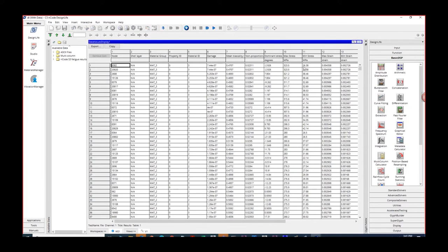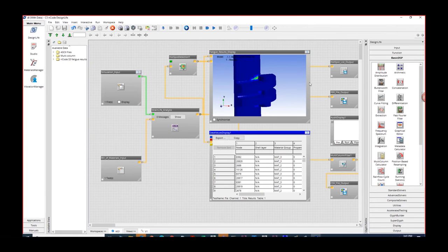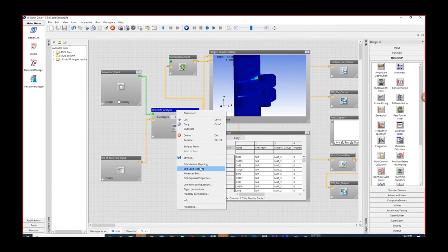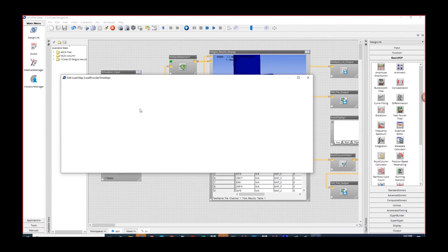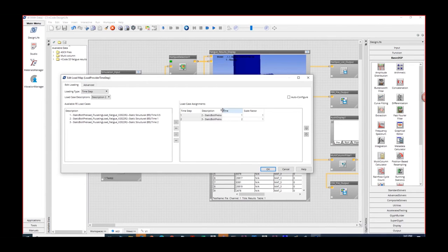And after the plasticity correction, the max stress comes to 323 and the min stress is 26.3. This is a little above the yield, but not too much like in the previous case. The important setting we need to make is to map the loading correctly, depending on whether it is a fully reversed loading or a zero-based reversed loading.